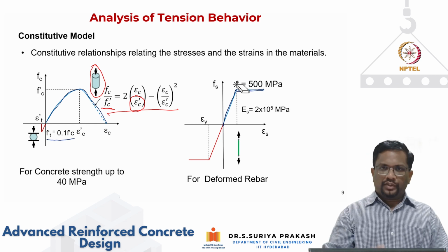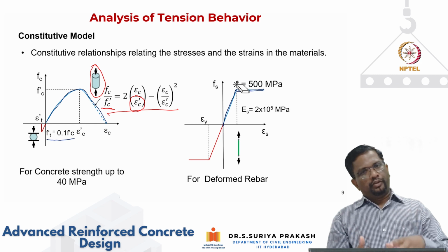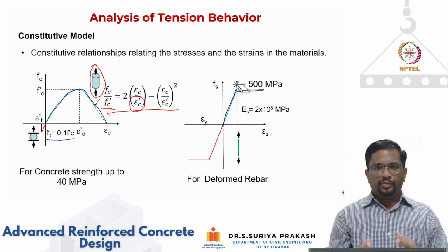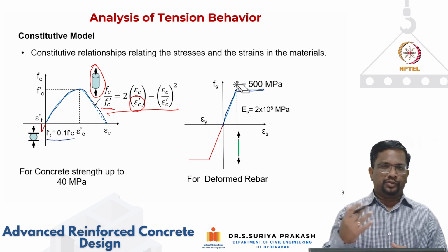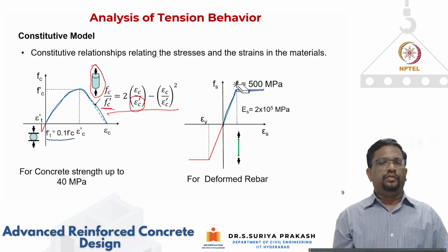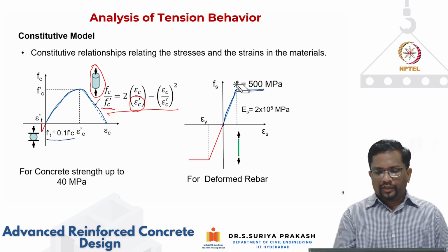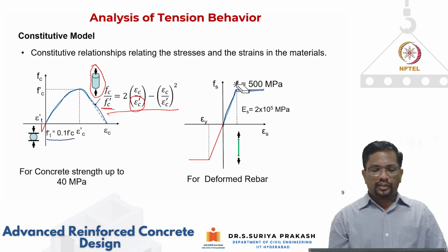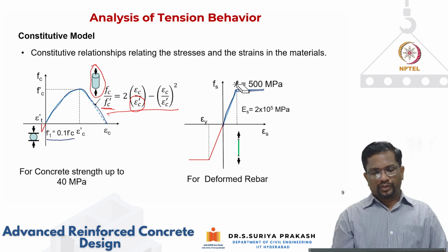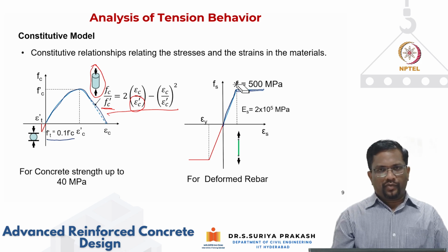And steel, as you know, is effective both in compression as well as in tension. But in compression we need to prevent buckling, and for column members especially, we need to make sure that we are having adequate transverse reinforcement and so on. That we'll discuss when we talk about column design in the chapter on columns. So this is the constitutive relationship for steel as a reinforcement that we are going to use in our calculations.